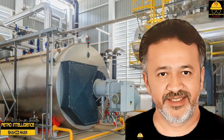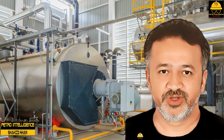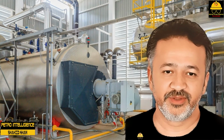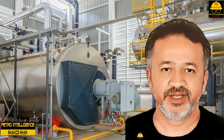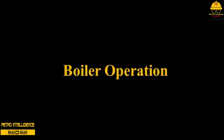Some plant processes cannot tolerate high temperatures. The process of cooling the superheated steam is referred to as desuperheating. During the desuperheating process, part of the superheated steam is returned to the steam drum. The cooler liquid in the steam drum removes heat from the superheated stream and allows it to be used in specific plant processes.